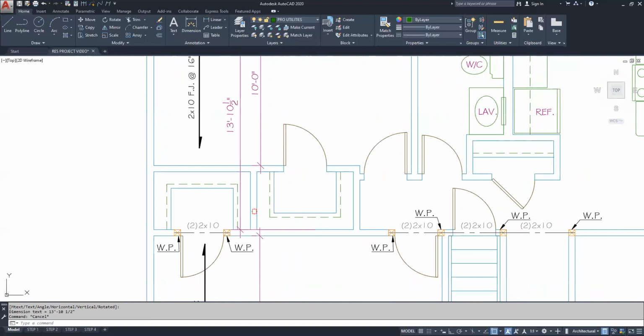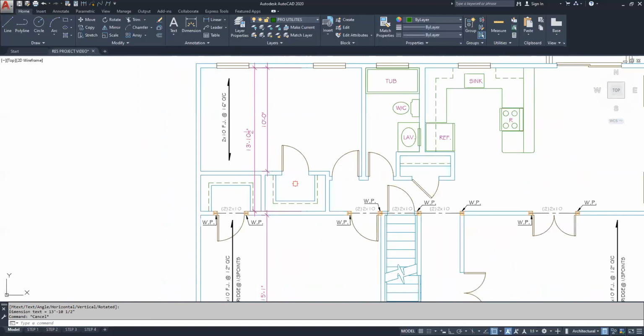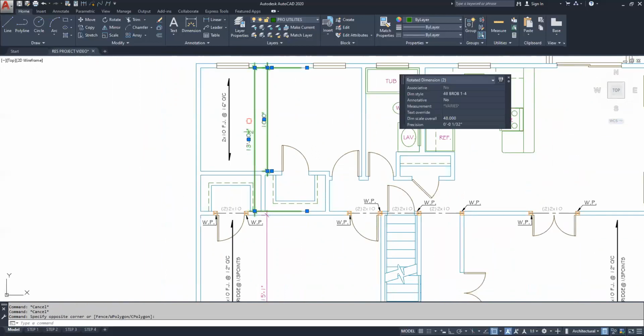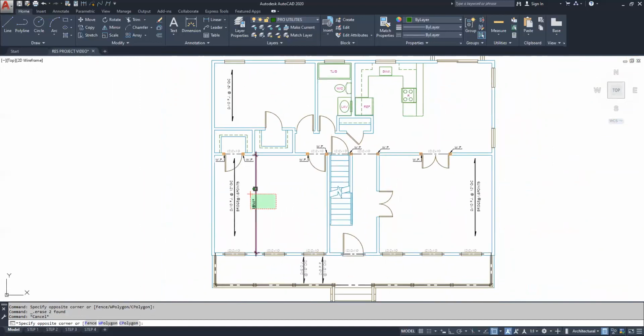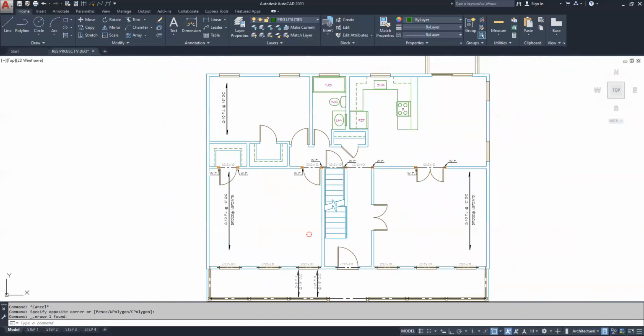It would be a good practice to go right to here, not to the closet wall when you're framing this out, so that they could take out the closets for some reason if they were redesigning the house. Some people don't always think about that, but it depends on what you want to think about. I think honestly that's pretty much it. Make sure you put the headers on the back windows the same as we did the front windows. The side windows here, label them. And that's about all.